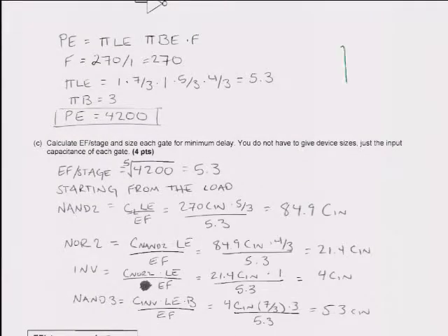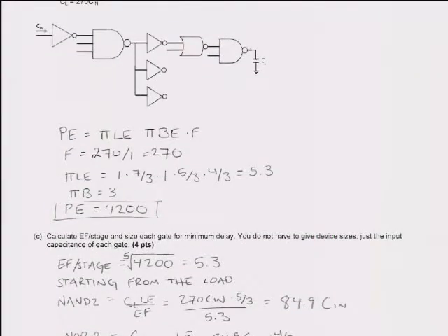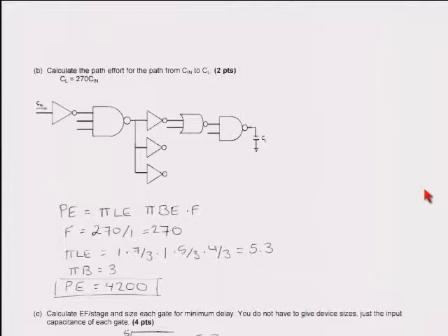And we can do the same thing. Let me just get back here. All right. So then we asked you to compute a logical path. There's a couple of inverters, one NOR gate, a couple of NAND gates. You can observe already that this thing is going to be NAND gate dominated. That's important for the last part of the question. There's also a little branching effort in here.